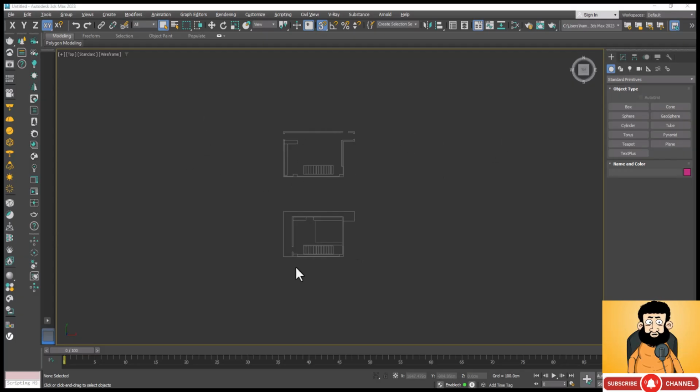Now, guys, since we don't have any volumes in our scene, when we want to work in the viewport and draw a line, we can put our snap on 3. But even if we have one volume, a three-dimensional volume, and we want to go with the line in the views, we have to put our snap on the 2.5. We have to definitely put it on the 2.5. Now, since we don't have any volume, we can put it on 3.